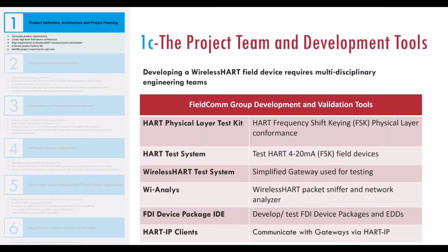And to that effect, the FieldComm Group does offer a gamut of different development and validation tools, which are listed here. Now, these tools are very useful when developing a WirelessHART field instrument, such as a HART physical layer test kit, a HART test system, a WirelessHART test system, the Y-Analyst packet sniffer, which is used quite extensively when developing a WirelessHART instrument, an FDI device package, and various different HART IP clients that allow you to develop client applications that will communicate with the gateways that you'll be using.